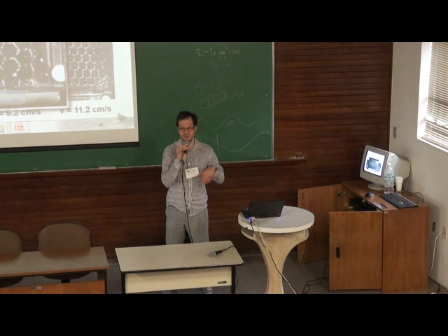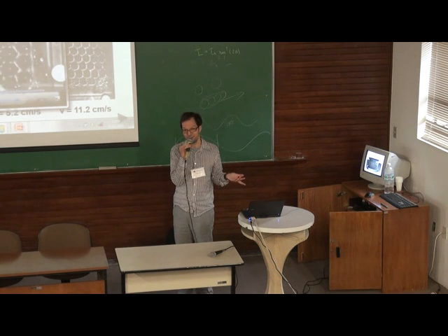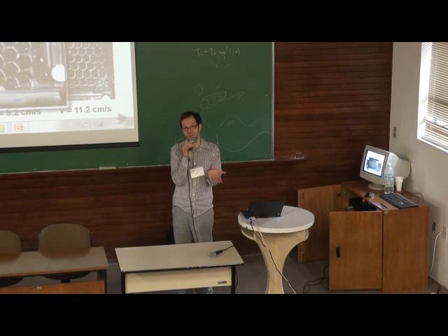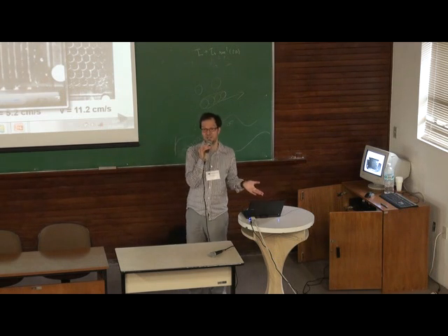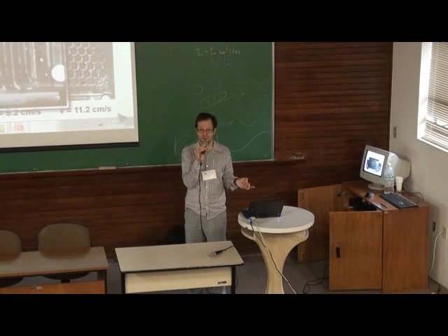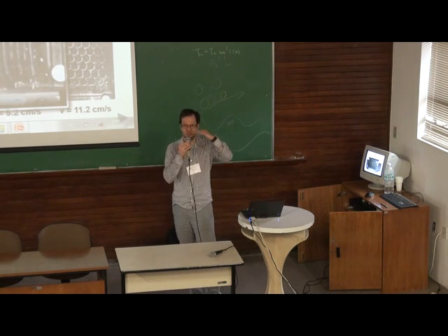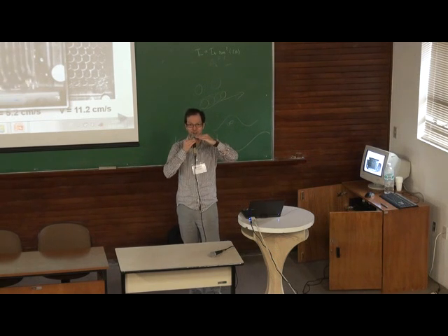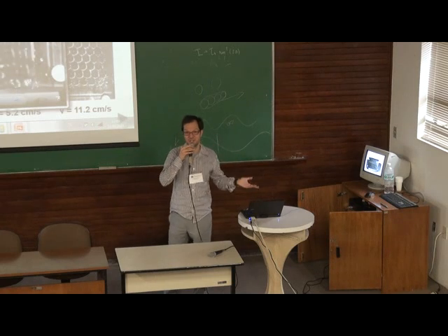So you have a small film of ferrofluid, you dry it on the spacer. That is a disadvantage. You have to dry it, and then you go into the vacuum of your transmission electron microscope, and then you take a picture and you make image analysis. This gives you a kind of estimate for the hydrodynamic volume fraction. But it is rather vague, because you have to know that your ferrofluid is thin enough that you don't get particles on top of each other and so on.